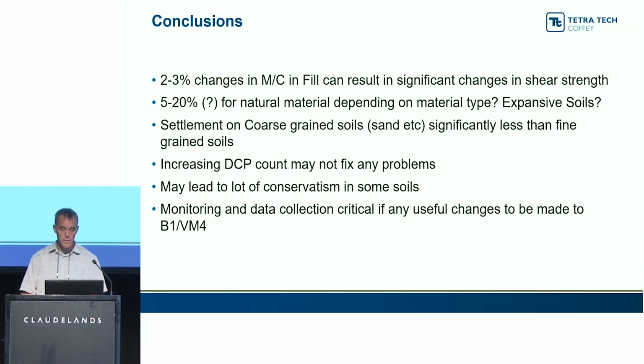Settlement on coarse-grained soils, sands, etc., is a lot less than fine grains. So there's a big difference between doing a DCP in sands and getting, say, 2 or 3 blows in sand. That's actually probably not going to be a big settlement issue. Getting 2 or 3 blows in clays and soft soils and fine grains may or may not be a settlement issue.